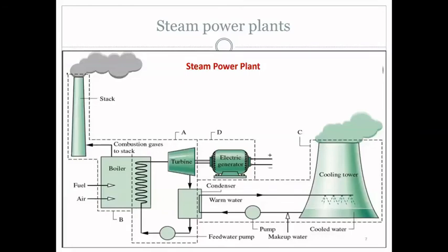In this figure, as you can see, we are presenting a steam power plant with all its sections. A steam power plant consists of a single boiler or group of boilers which heat the water and turn it into high pressure, high temperature steam, which moves by a piping system to a three-stage turbine, which produces shaft work, transferred to an AC generator.